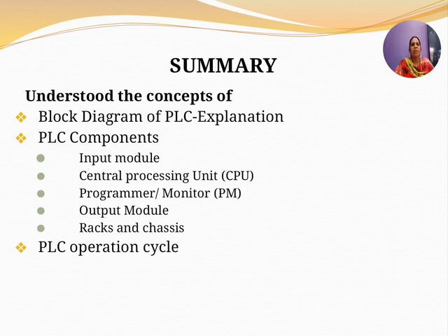The power supply module is used to provide the required power to the entire PLC system. It converts the available AC power to DC power, which is required by the CPU and the input output module. So the PLC generally works on a 24 volts DC power supply. Few PLCs also have isolated power supplies.